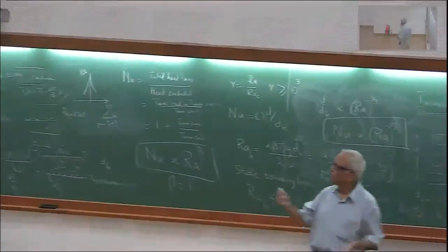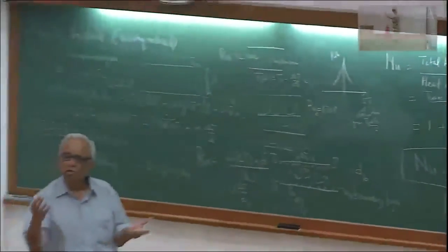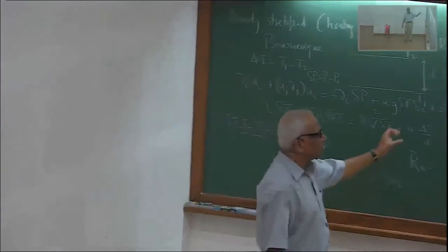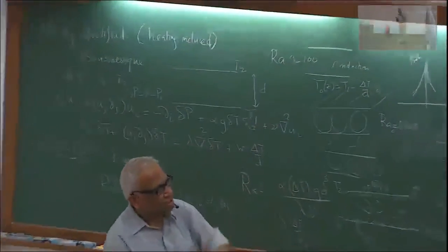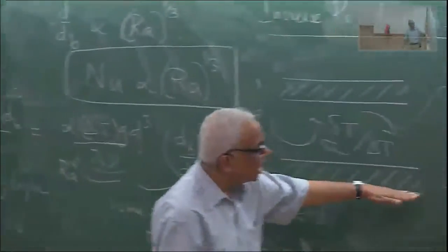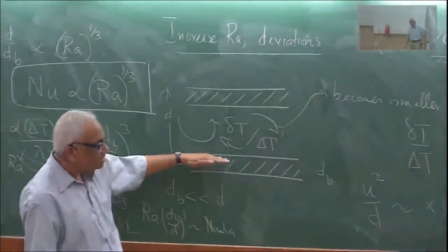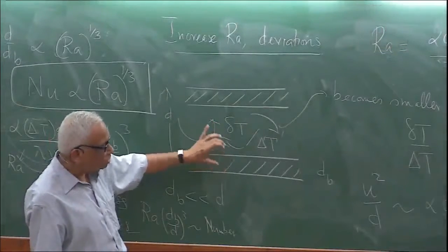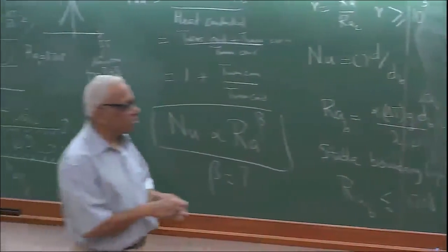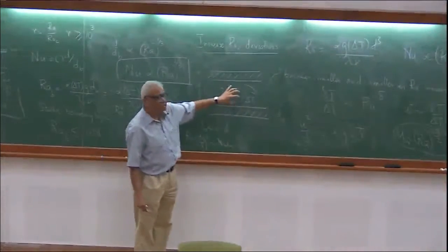After all, these viscosities, nu, are of the order of, in CGS units, 10 to the power minus 2, minus 4. If it's water, 10 to the minus 2. So this is operative once again in a region where the velocity has to be zero on the boundary. That's viscosity playing the game for you. And then it changes rapidly in what is called a boundary layer. That is when this term is very effective. Thereafter, the viscosity is no longer a player in maintaining the velocity over here.